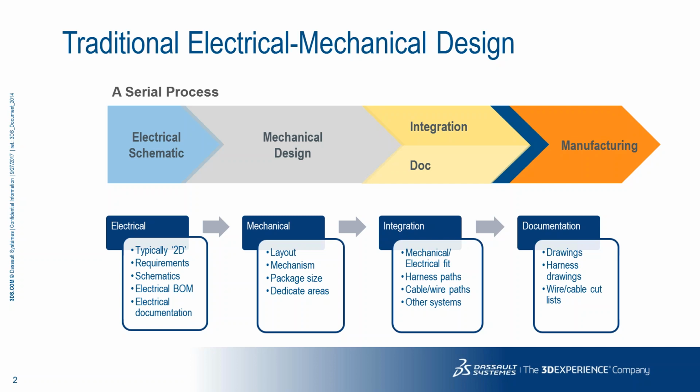For example, the bill of materials. The electrical schematic designers cannot get the actual wire length unless they have a mechanical perspective. In some cases, they just imagine that, yes, we can make holes somewhere in the enclosure, but in fact the mechanical designers cannot do that because there is a fan. And we all know that in electrical schematics, we always design things in 2D, and in most cases we don't have a good perspective of the actual dimensions of these components.